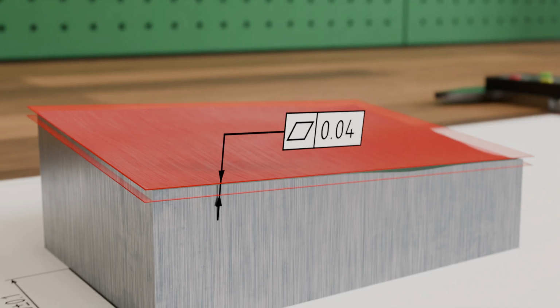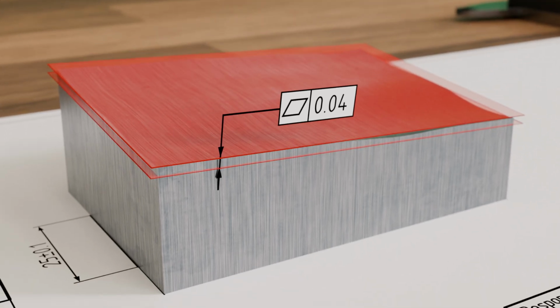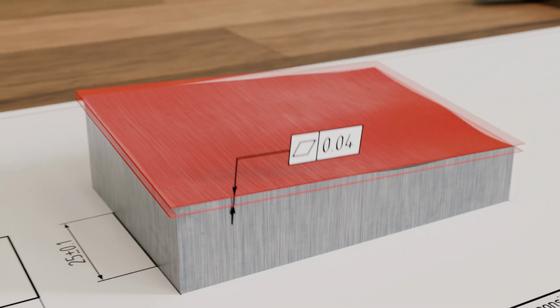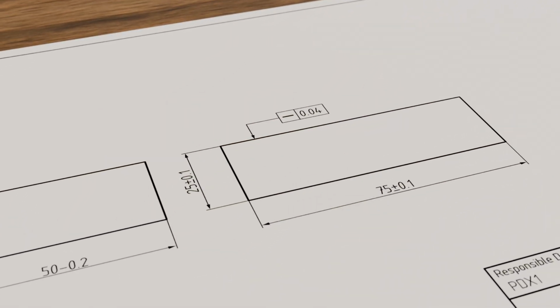As long as the tolerance geometric feature, in this case the component surface, lies between the two imaginary parallel planes, flatness according to the form tolerance is fulfilled. Flatness thus imposes no restriction regarding the position of the surface. To achieve parallelism of the surface to the bottom side, positional tolerances are again required, which will be covered in another video.